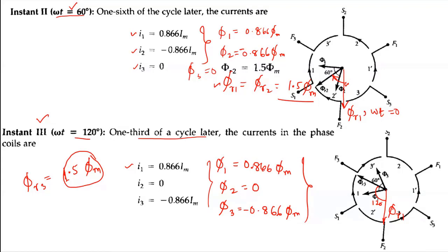The magnetic field rotates with a constant magnitude in accordance with the current waveform, right? Okay, so that means your resultant flux is rotating with respect to the current waveform. As the current waveform moves, your resultant flux also rotates. So this is the conclusion.